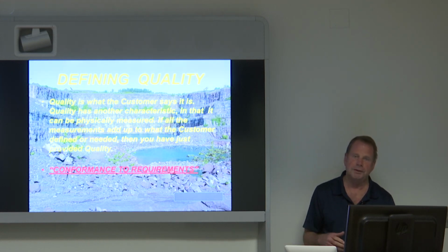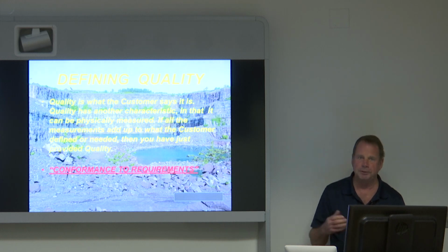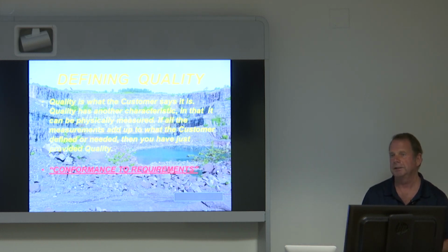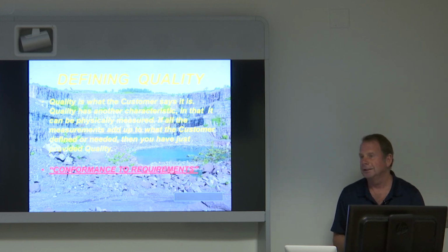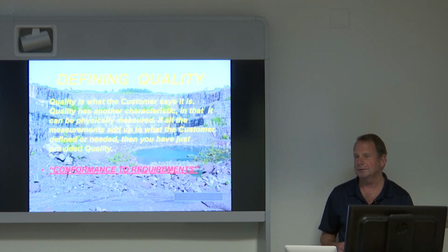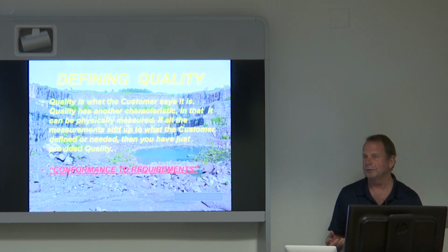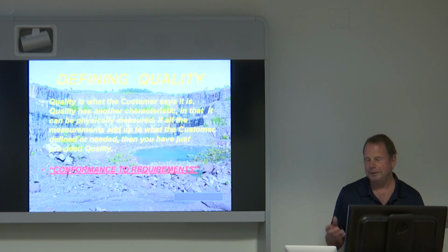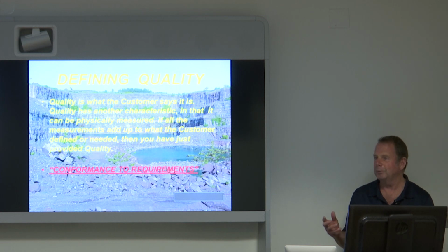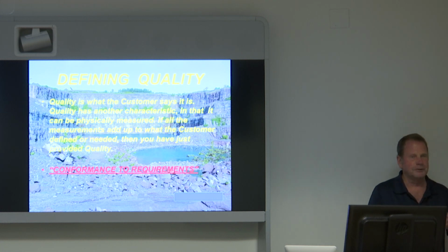When they bring it out to the plant and dump it on the ground and push it, they rack it up into the stockpile and it starts all over again, right? When you guys load it into your cold feed, and then just take it beyond that. So you ran it through your plant and did everything right there. And you kept your silo full when you were loading the trucks. And it went out to the paving crew, and they didn't do their job right. They let the hopper run empty and lifted those wings up on the paver. And so every 20 yards, you've got a segregation in the road. I know you've all seen that out there.